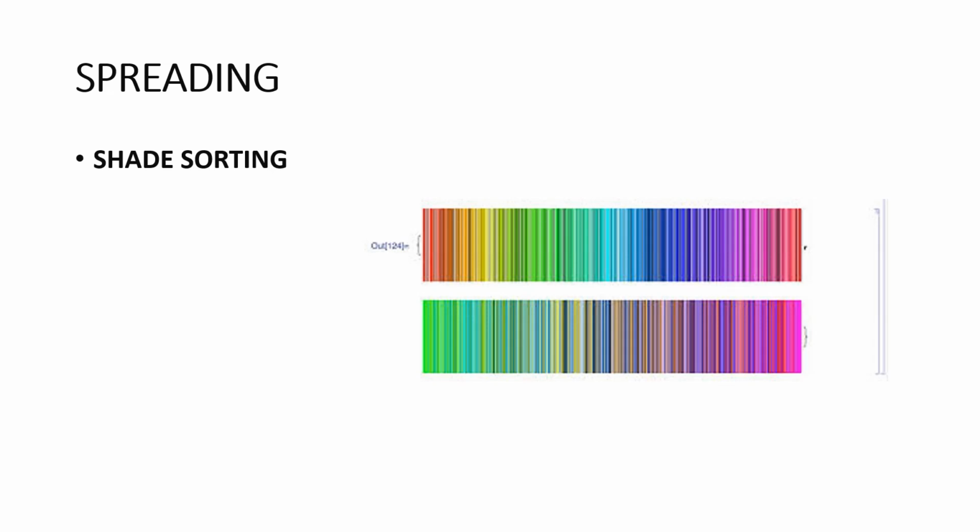Violet also. So in this fashion, if there is a little bit of variation in the shade, and those are coming into the spreading operations, when fabric lays one after another are being given, similar group of color or similarly sorted colors must be there in that fabric lay. Otherwise, if it is mixed together, there will be variation when the cutting operation is done and assembly is done in sewing. So there will be variation in different parts of the garment, because we have to join with seams and all these in the garmenting stage.